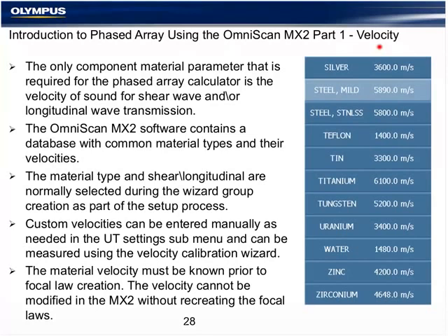When you recalibrate velocity in the OmniScan, you're actually rebuilding the focal laws. And this is true for all software. It's just a physics thing more than a software limitation. So you must know the velocity. Normally, for carbon steel weld inspection using normal P numbers and typical API piping, selection of the velocity from the database is just as accurate as your ability to measure it for the delta.